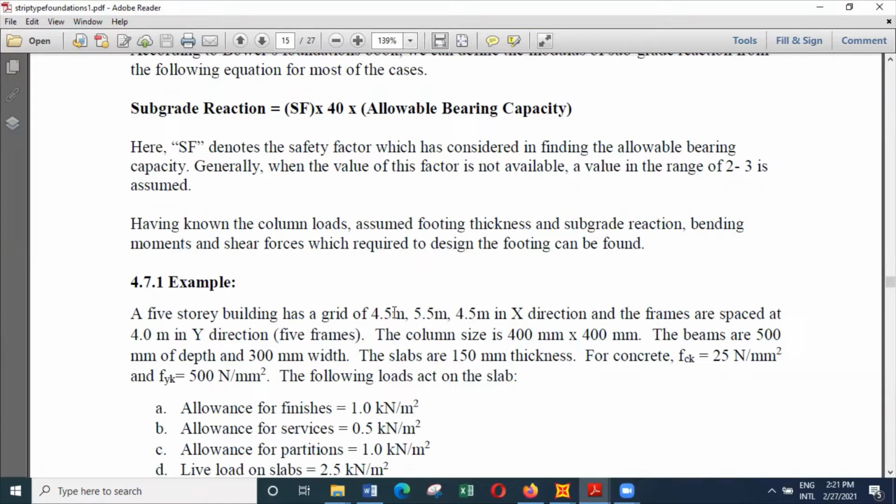Generally in Eurocodes, there isn't much restriction on the use of type B reinforcement. In certain instances, you will find type A is not encouraged, whereas there's no restriction as such for type B reinforcement. And type C is used in areas having very high seismic activity, because its ductility is even higher. So we are using type B reinforcement.